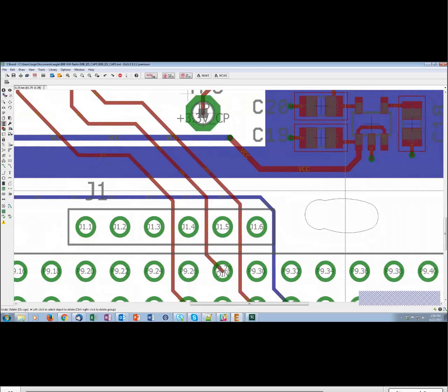And like I said, you can enter specific points. So for example, with the slice tool active, I can just type in 61.75 and 61.75, 6.75. So the idea here is just to illustrate that you can enter a specific point. So I hit enter, and now if I use a delete command, that's where the line went through. So it's very easy to control it and to specify where you want the cutting plane to be, or the cutting line to be more accurate.